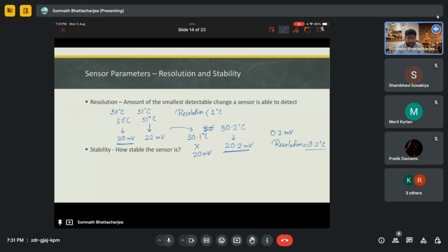If there is a very sensitive case where we have to maintain a temperature of, let's say, 270 degrees centigrade for a specific material, and even if there's a slight change to 272 degrees centigrade the material will corrode, then we need a temperature sensor which can detect at least a 1 degree C change. The resolution of the temperature sensor should be 1 degree C. That's why, whenever it's reaching 271 degrees centigrade, we'll get to know and will then reduce the temperature in that furnace or something.